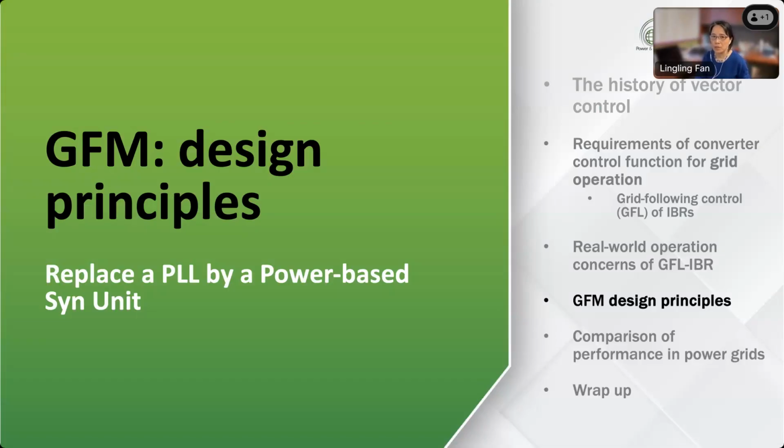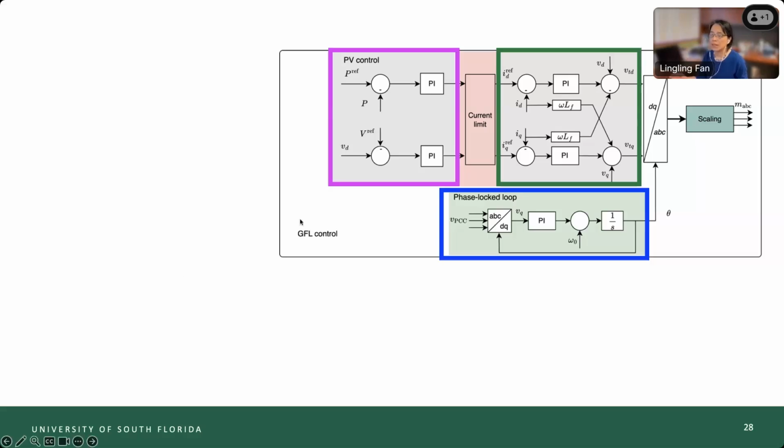People have benefited a lot, and we don't actually want a very radical change of everything. In particular, the current control is really nice. You can explicitly regulate the current and apply a limit there. If you change everything to voltage, how do you apply this? It's very difficult. So in the structures we discuss today, we all have this inner current control loop intact.